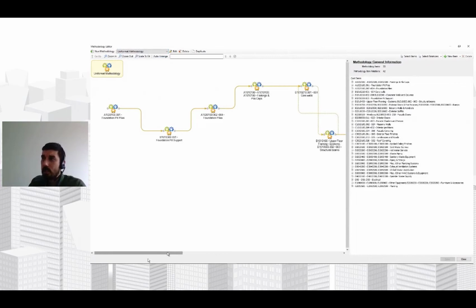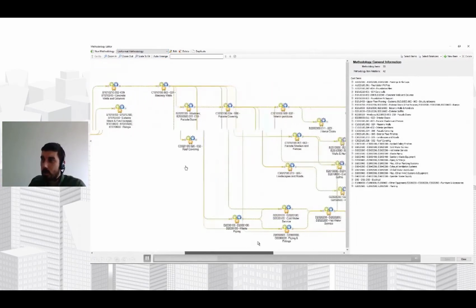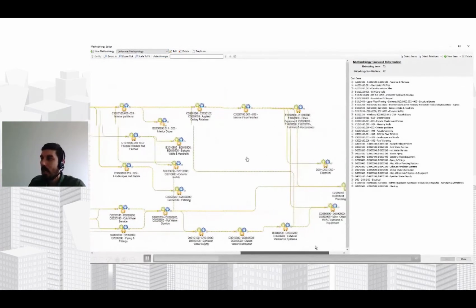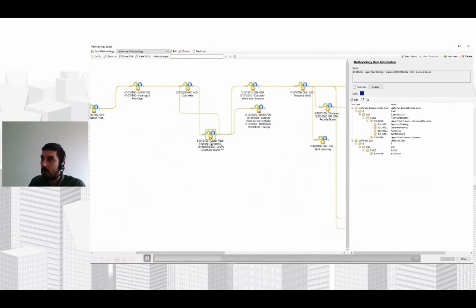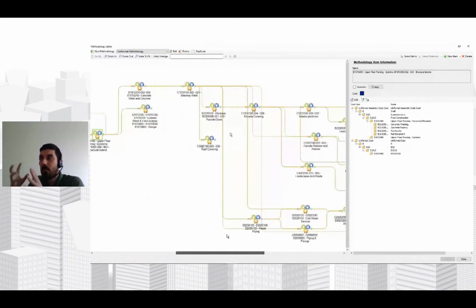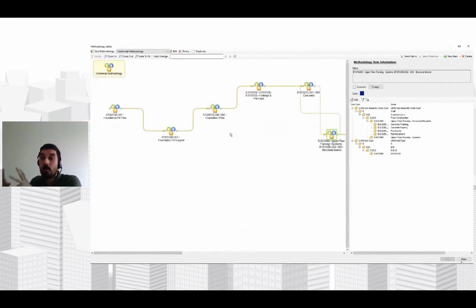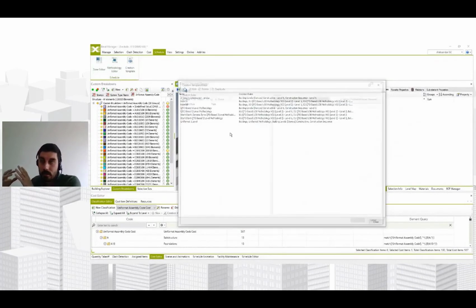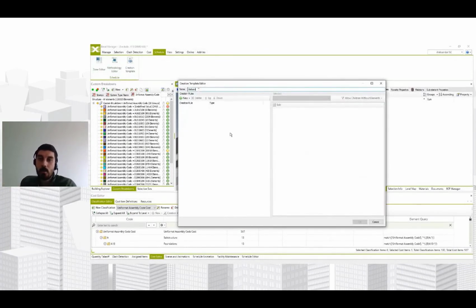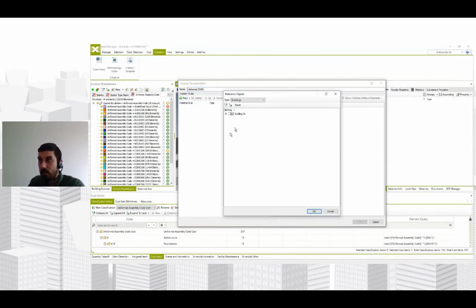Of course, to do this for the whole project would take too much time for a presentation. But this is how, for this demo project, the completed methodology looks. So we have the nodes, and we have defined relationships between different groups of works, and those groups of works are related to the model elements. So based on this, we're going to create what we call a creation template. We're going to combine these zones and methodologies into one single template.